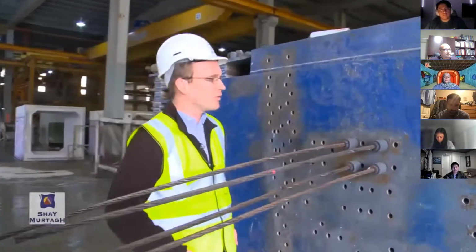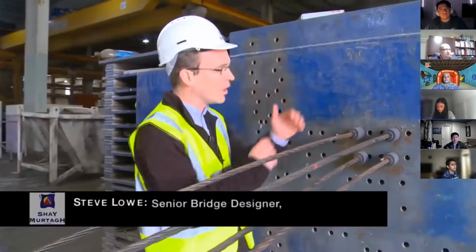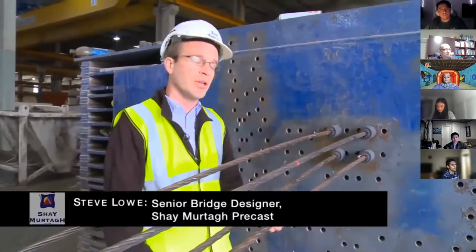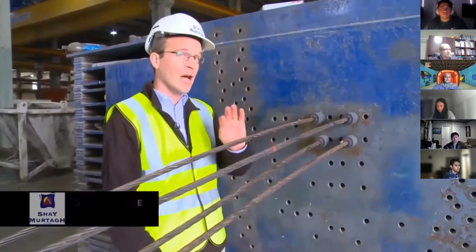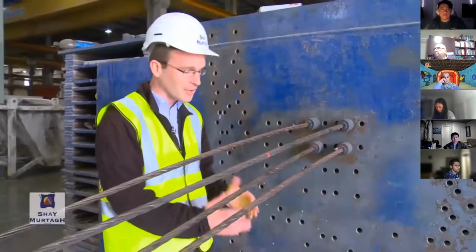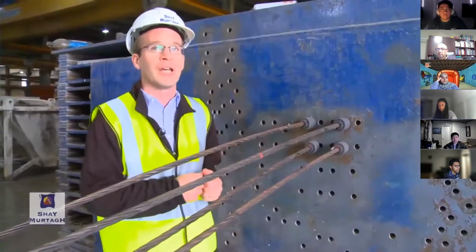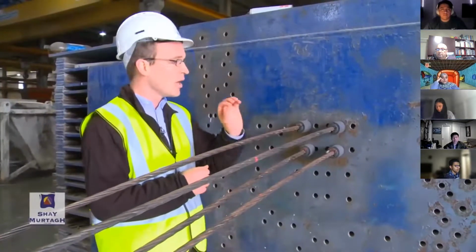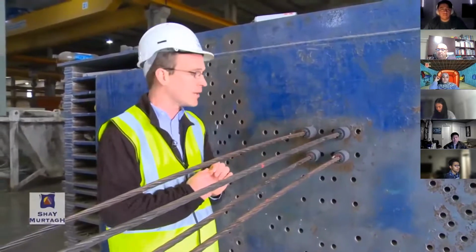Okay, now here is our typical stop end that would be used to orient the pre-stressing strands that we would use to apply that compressive force to the beam end. Now note, these strands are not in tension, they're slack, so there's no danger here. You must be very, very careful with fully tensioned pre-stressing strands, because there's a massive amount of force that can be contained in each of these strands.